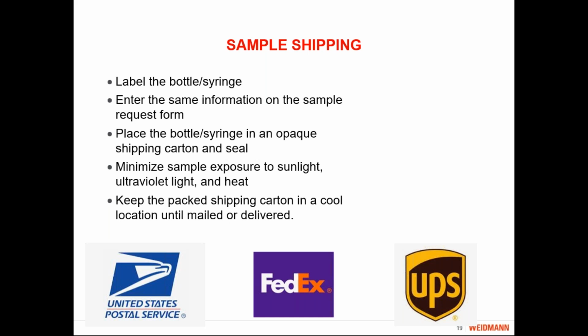Sometimes people say, well, how long can I sit on this sample before I should send it in? And the answer kind of depends on how accurate you want your sample results to be. From DGA, our studies have shown even if your syringe has perfectly good seals and it's all functioning properly, you can still lose approximately 1% of the gases that are dissolved in that oil per week until it gets sampled. So at Weidmann, we generally would like to get that sample within 5 days of the sample having been taken.